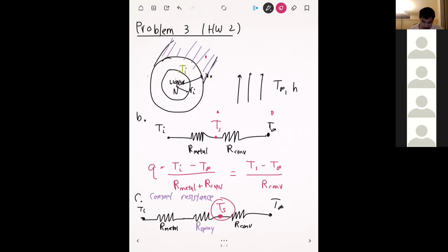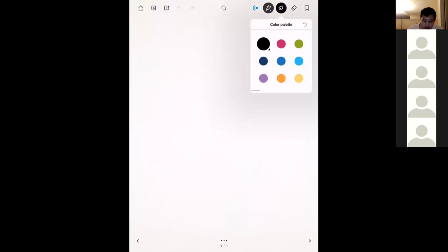And so for part D, you're going to be adding another layer of insulation on top. I think this is where people get confused, because the contact resistance is still there from the previous part. We're just putting something additional on top of that. So now we're going to have 4 resistances in total, and our thermal circuit is going to look like this.